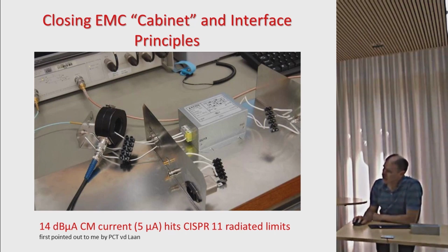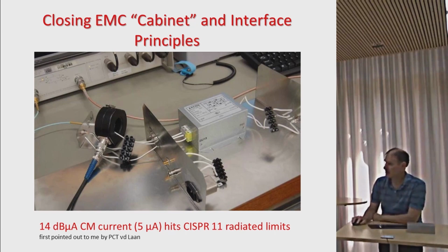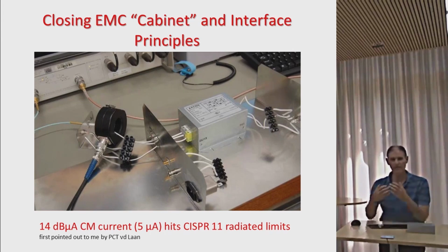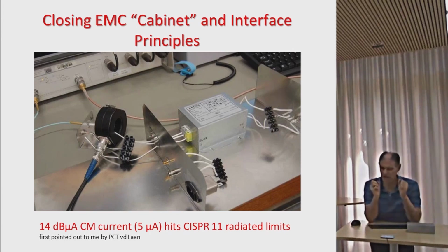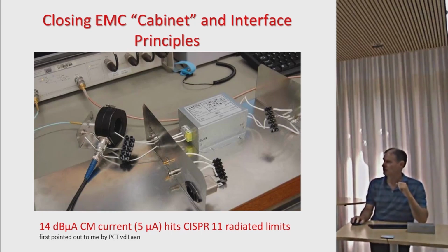You will see I've got various connection options here, and in one of them, we just literally put the wire through a hole in the wall. If we do this, what happens is energy from the outside goes straight through the hole in the wall, goes onto this filter, and if I pick the filter up, that energy can go underneath the filter, go to this wire, go out through a hole in the wall and back to where it came without even going to the filter. Look, you're getting a clue that what I'm doing there is saying, if you don't visualize what your currents are doing, you can completely get rid of the properties of something you intend to have a purpose like filtering.